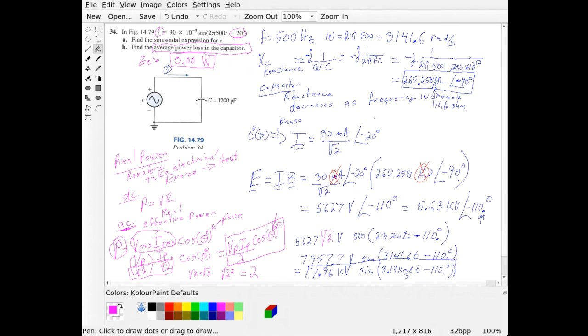For an inductor, the only difference is the inductor is storing the energy into a magnetic field for half of the cycle and then dumping it back into the circuit during the other half of the cycle. So inductors and capacitors do not lose power. The power stays inside of the circuit.